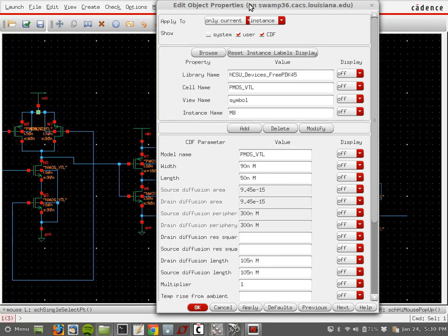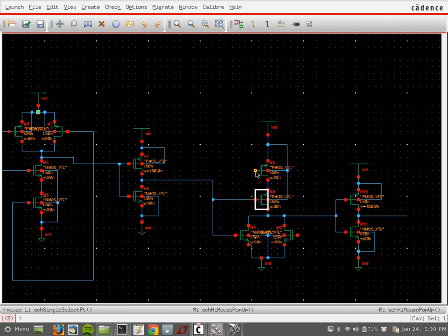It's ratioless in that the value will always reach either VDD or ground, but it won't be symmetric unless the sizing is correct. It always reaches VDD or ground, but not at the same speed. As long as we know the mobility of the PMOS is twice that of the NMOS, we just make the PMOS twice as large as the NMOS. Yeah, that's what we did in the inverter, right?